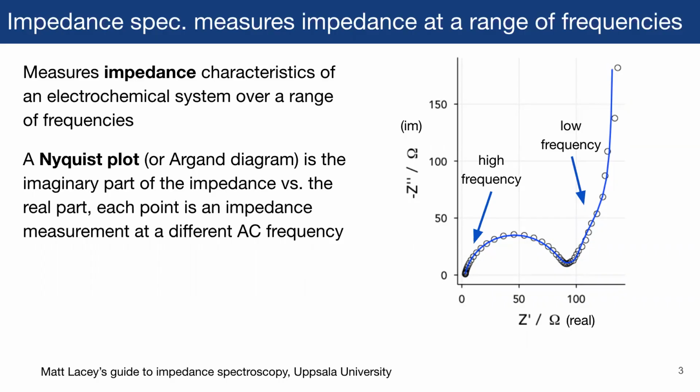And in the process of measuring that response, really you're measuring the impedance, because the impedance is an alternating current phenomenon. EIS plots are usually displayed in a Nyquist format here, where you plot the real component of the impedance against the imaginary component of the impedance. And you plot the points throughout all the frequencies. So high frequencies are going to give you lower impedance, and low frequencies are going to provide much more impedance.